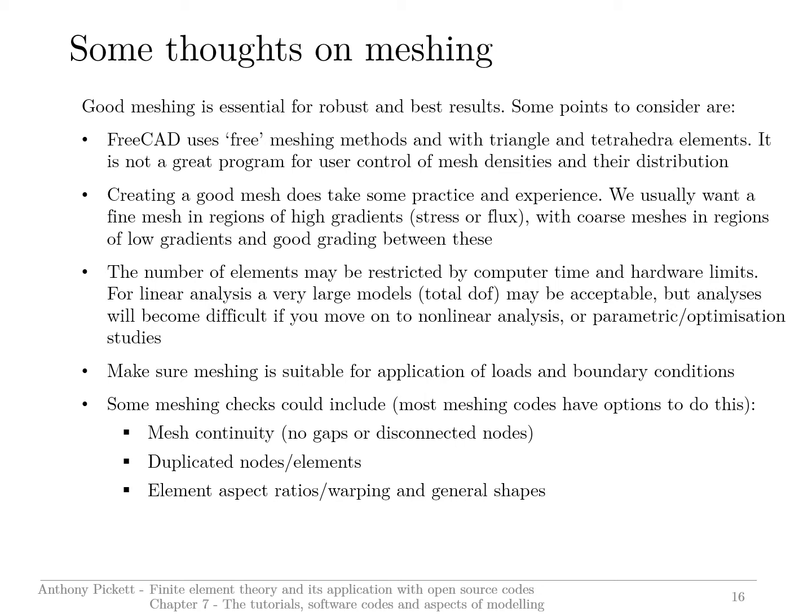Of course, with modern computers and fairly small problems, you could take the view that you just use a very fine mesh everywhere, but this is not usually very good practice, and you can quickly run into problems if you extend the analysis to nonlinear analysis, or you do parametric studies or some kind of optimization of a structure which requires a lot of analyses. Then the computing time for a very finely meshed model could become excessive. You've got to make sure the meshing you use is suitable for the loads and boundary conditions that you want to apply.